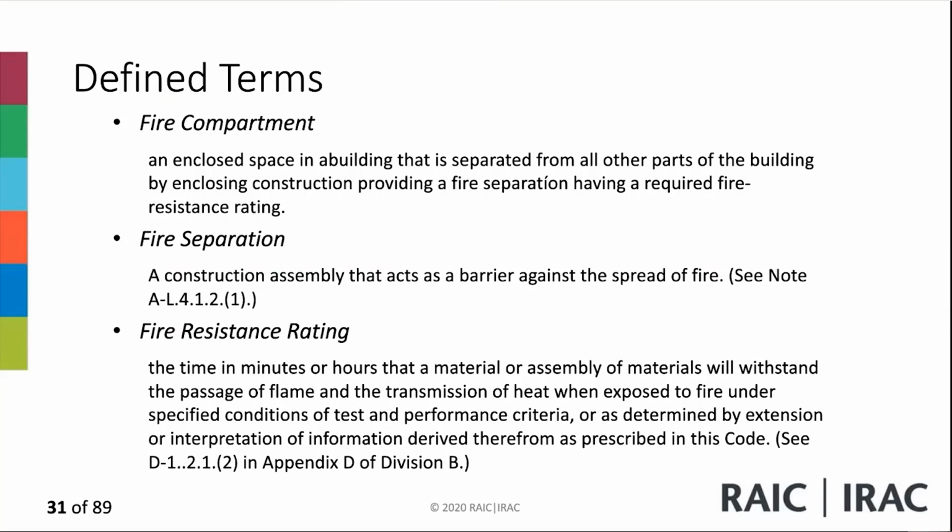Since it's not practical to measure the fire resistance of construction in situ, they must be evaluated under some agreed test condition. A specified fire resistance rating is not necessarily the actual time the assembly will endure in situ in a building fire, but it is that which the particular construction must meet under specific conditions, specified methods or tests. So here what this is explaining is that the fire resistance rating is determined based on a specific condition of a test, and it compares the performance of one assembly to another, and the code provides certain criteria based on this, and this is the minimum performance.